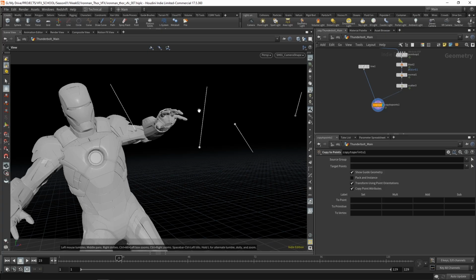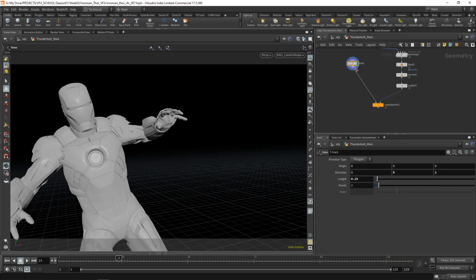It would be nice for us to have a gradient on each one of these splines, so we should have a curve view attribute on these as well. As for the main ray, where we didn't want to displace the tips, the extremities of the main spline, here again it's the same thing. We don't want to offset this point. Everything else can go crazy, be completely distorted, but the first point needs to be kept intact. So it's good for us to have a curve view attribute.